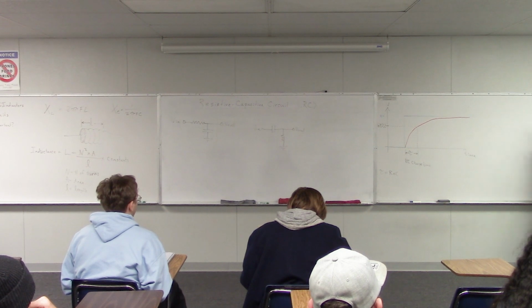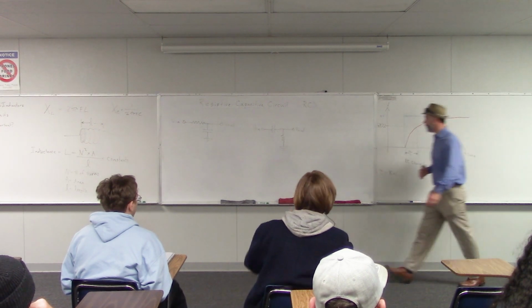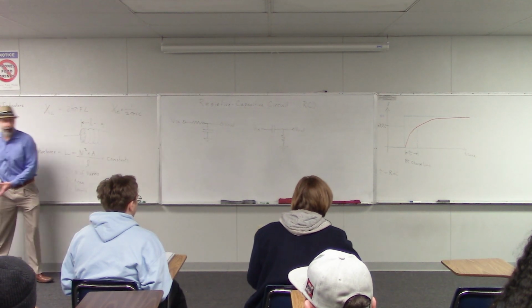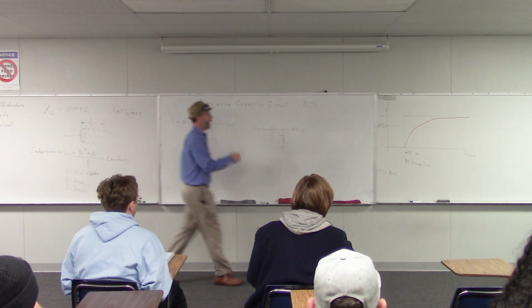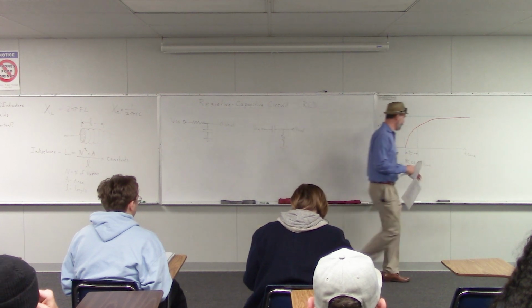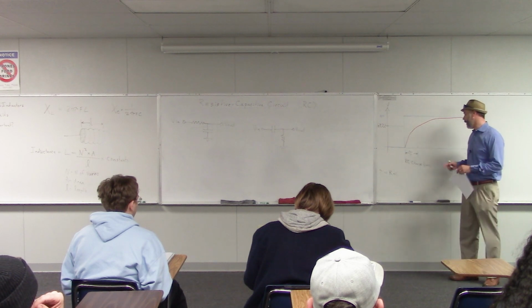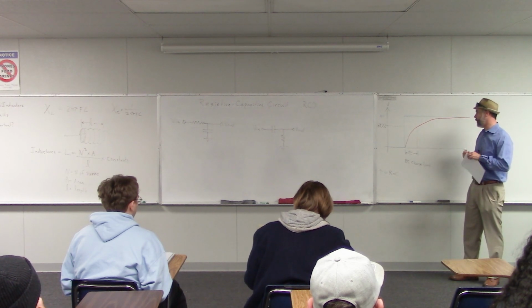Well, what happens is that you can measure how much a capacitor has charged up after various numbers of these charge times. So after one charge time, the capacitor is up to 63.2%.